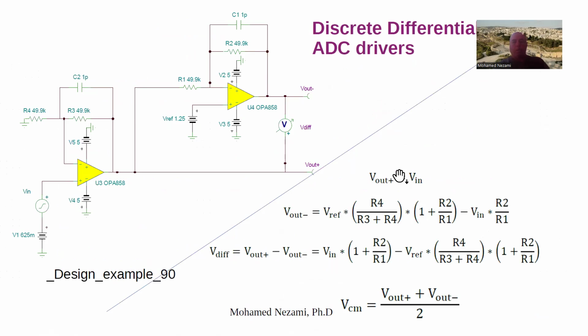All right, this one I didn't correct it, but let's go with it. This circuit in here doesn't correspond to these, but let's just imagine if these resistors were these resistors in here. I didn't get a chance to correct this one. First of all, the simplest way to do a differential amplifier is to take a signal and buffer it, and take the output right here. So that's one of the outputs, the positive output.